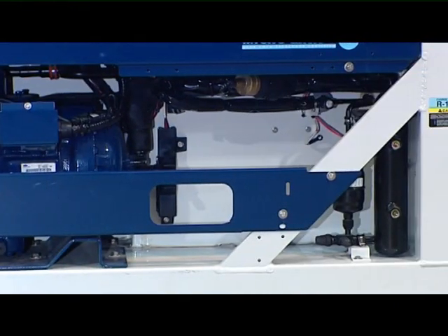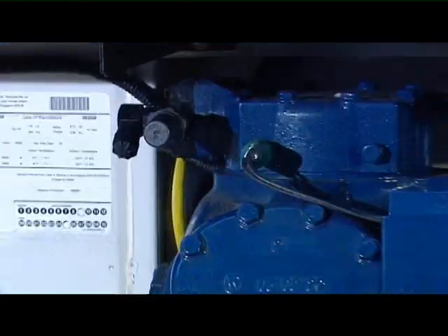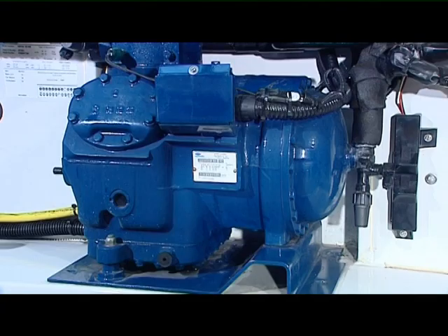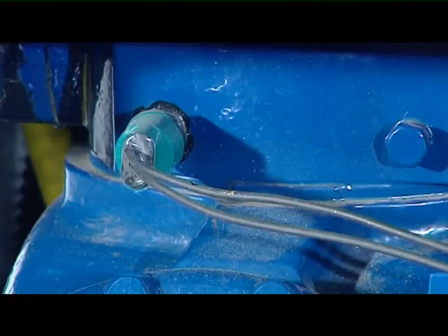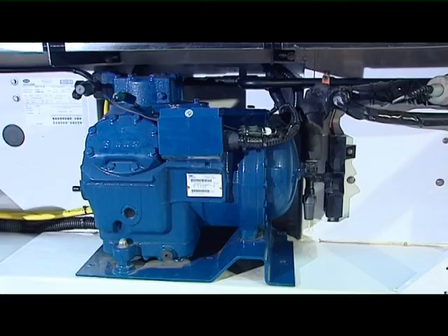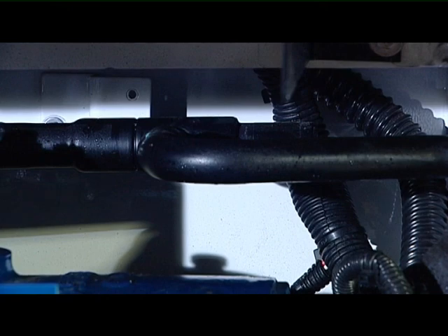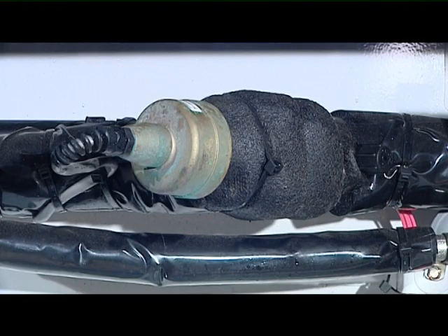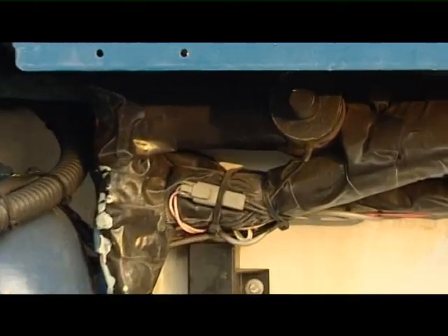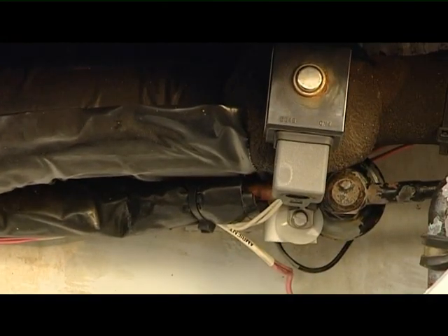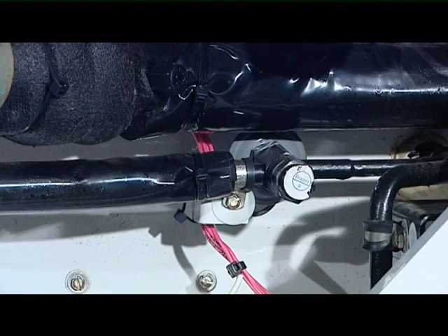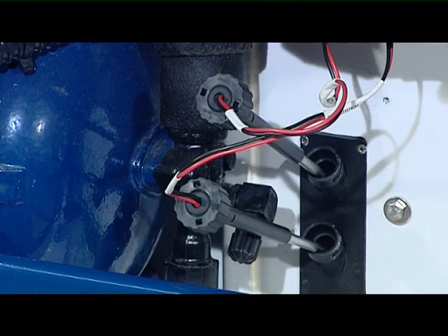The compressor section includes compressor, discharge valve, suction valve, high pressure switch safety, pressure regulator valve, stepper suction modulation valve fitted on the newer units, which replaces the suction modulation valve and the suction solenoid valve for the older ones, quench valve, and supply air sensors.